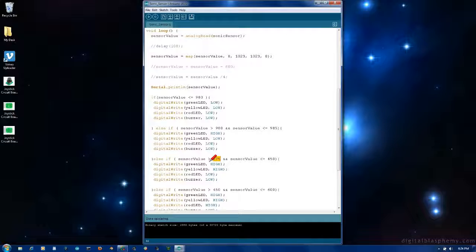And then we're going to do another piece of code that says when we push the button and let it go, the light stays on, and we push the button and let it go again, the light goes off. So you may think a push button would be very simple compared to what we're doing here, and it is, but it's not so simple as just a digital read to see whether the pin is high or low.